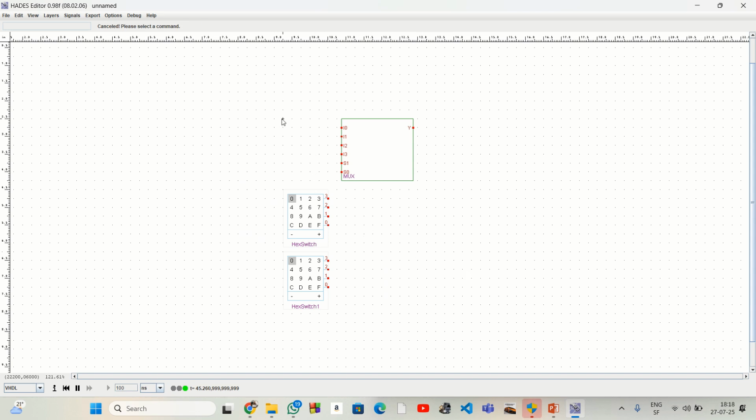Then over here, I'll have the input switches. So I'll create IO, I-pin switch. So I'll have 4 of them. So that's why I'll have 1, 2, then 3, and 4. The name of this is I0. The second one is I1. The third one is I2. And the last one is I3.